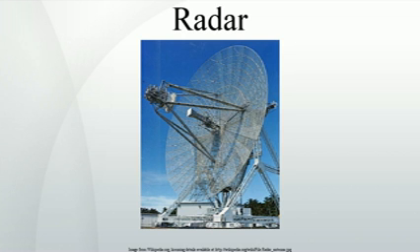Radar coolant. Coherent microwave amplifiers operating above 1000 watts microwave output, like traveling wave tubes and klystrons, require liquid coolant. The electron beam must contain 5 to 10 times more power than the microwave output, which can produce enough heat to generate plasma. This plasma flows from the collector toward the cathode. The same magnetic focusing that guides the electron beam forces the plasma into the path of the electron beam but flowing in the opposite direction. This introduces FM modulation which degrades Doppler performance. To prevent this,